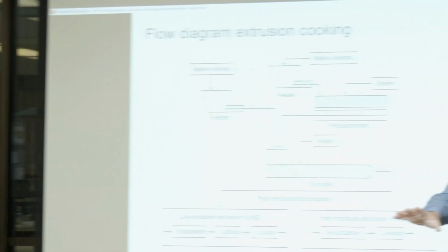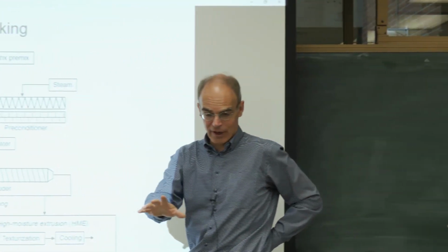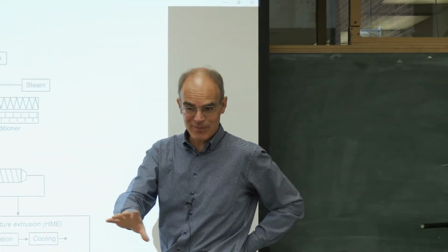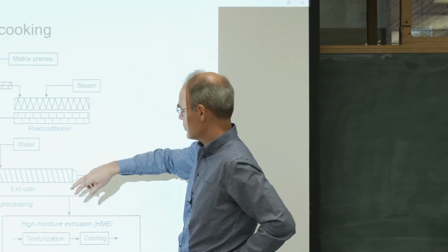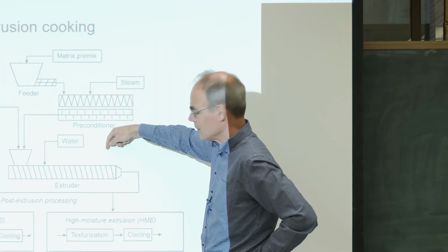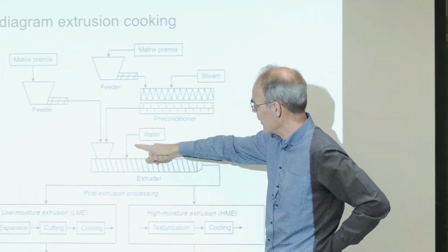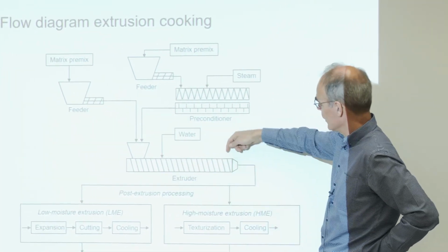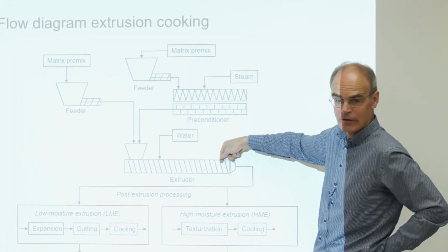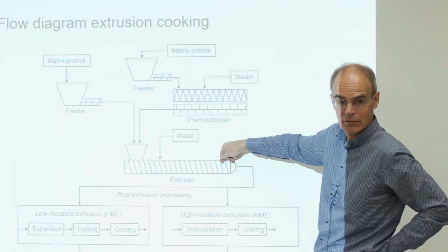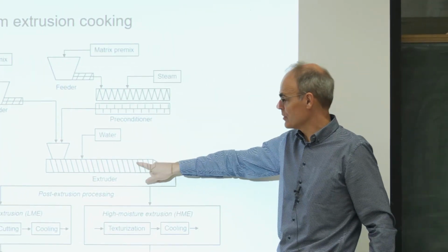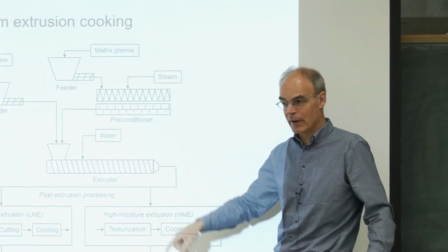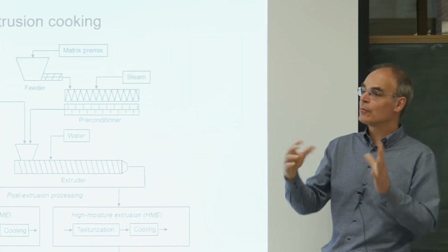Yeah, actually I've been doing a lot of that work, not for meat analogs, but for making encapsulation systems based on starch. So you can definitely do that, we can actually do that in the screw simulation. We can set it up. What you can do here is have a port to inject water. You can create a screw design where you can inject an oil or a flavor, and then you can mix that in. So you can do that just before the die, but you still have to do that in the extruder barrel, because then you can mix it, you can disperse it in that matrix.